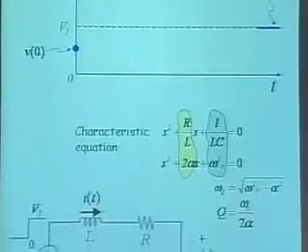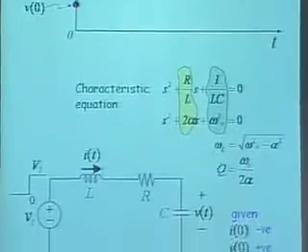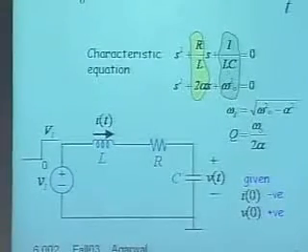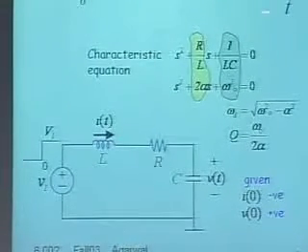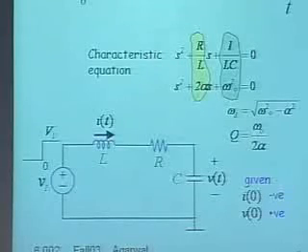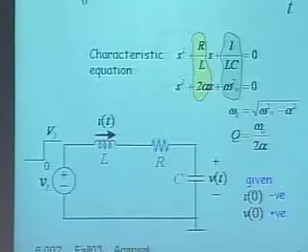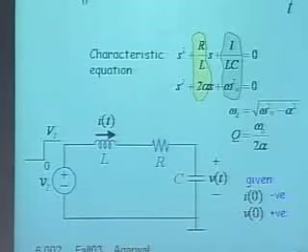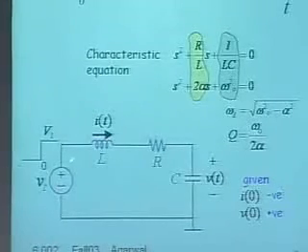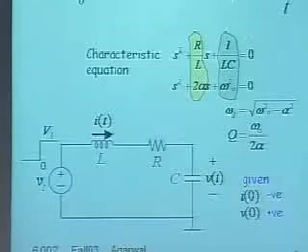So let's see. As a next step, I need to understand what the dynamics of the circuit look like here. So I develop the characteristic equation, and initially you'll write the differential equation and substitute e to the st and get this characteristic equation. But you can also remember it as a pattern. For a series RLC circuit, you always get an equation of this form.